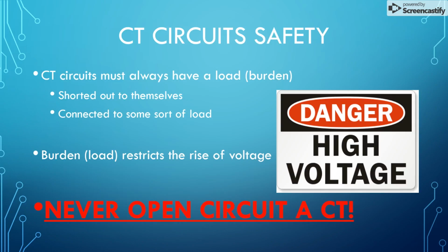So some CT circuit safety: CT circuits must always have a load or a burden. They either need to be shorted out to themselves or connected to something. We can't just have a CT with a secondary open and not going to anything. It's very important to understand that the burden, or that load, restricts the rise of voltage. We can never open a CT circuit. It presents a very dangerous, very high voltage.